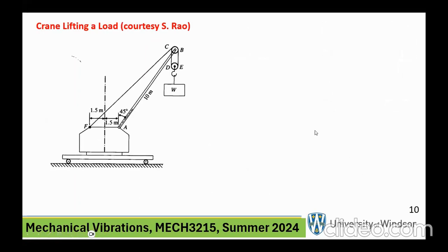Now, here's another example where you have a weight hanging from this effectively. Remember, this weight can oscillate up and down, right? Its mass can also. And what is resisting that? There's this bar with the stiffness, if you want, AE over L, if no bending was involved. But if there's bending involved, it's more complicated.